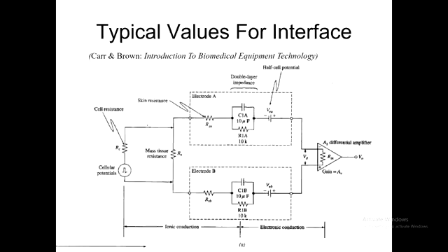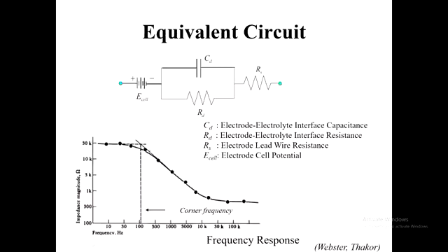So that helps us to determine any time constants. Once we know that particular time constant, the reciprocal of that will tell us what the break frequency is. So we can characterise the impedance behaviour with frequency. The takeaway point here is that for this particular scenario, the impedance is high at low frequencies and drops down at higher frequencies. So bandwidth limited at the electrode.